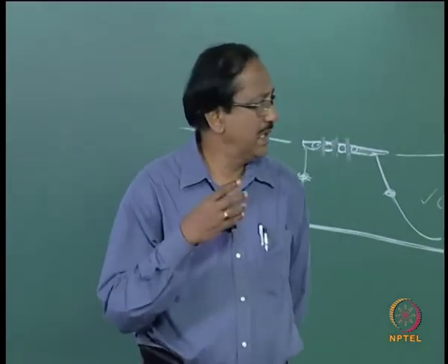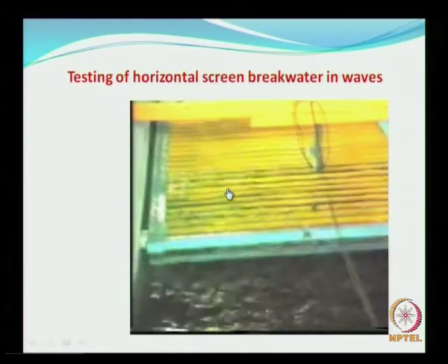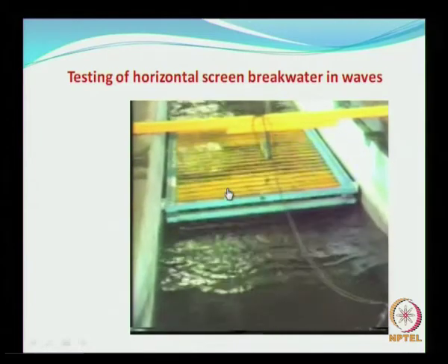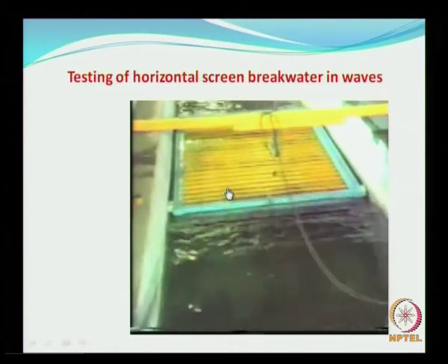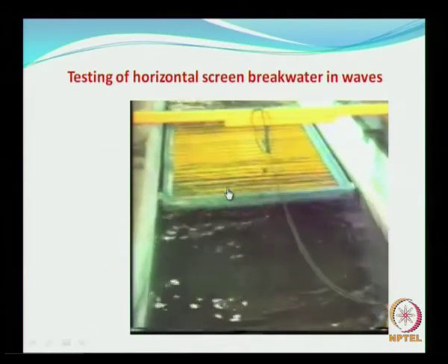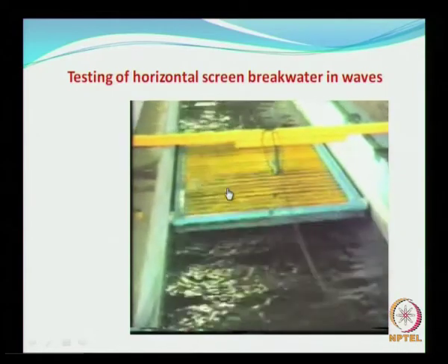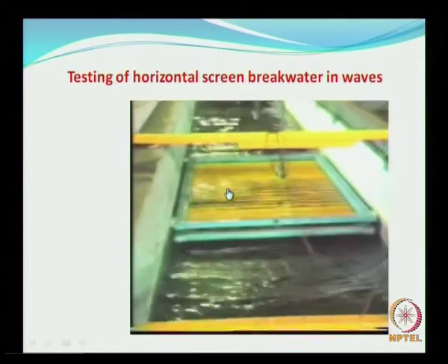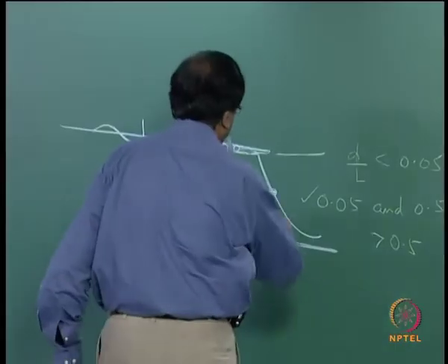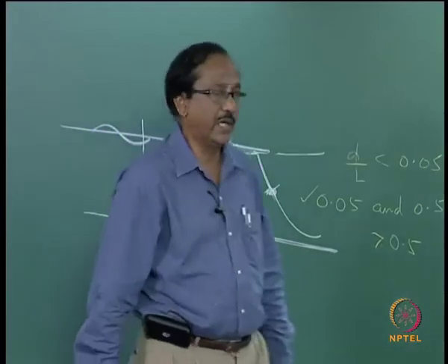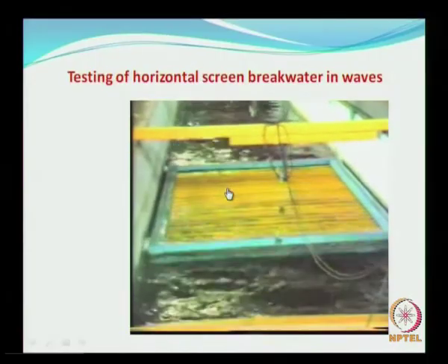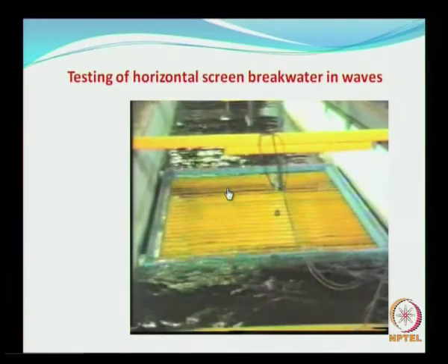Floating breakwaters are useful mostly when you want to create a calm area in the ocean for carrying out a specific task over a short duration of time. So this was a study, and here we use what is called a pulley system to measure the motions of the structure, as well as a load cell for measuring the forces on the mooring line. I would not go into the details of these studies, but such studies have been carried out using this flume.